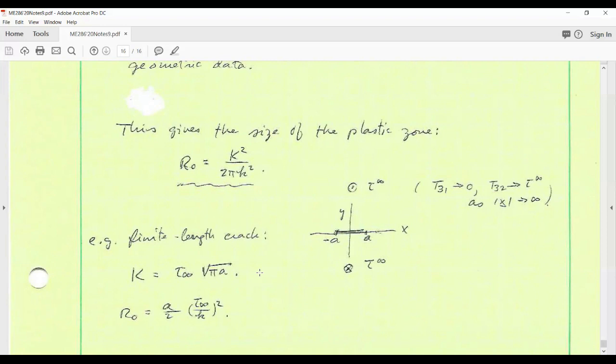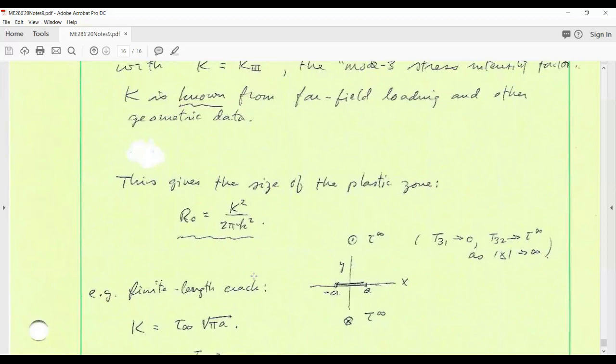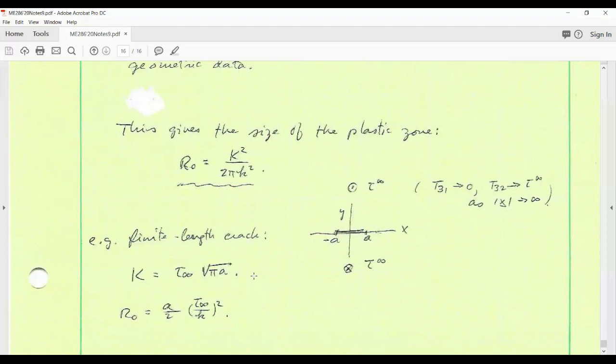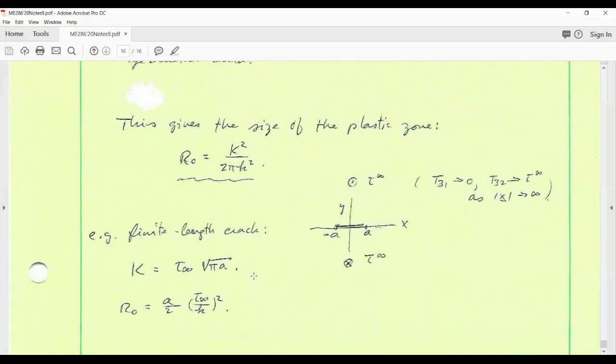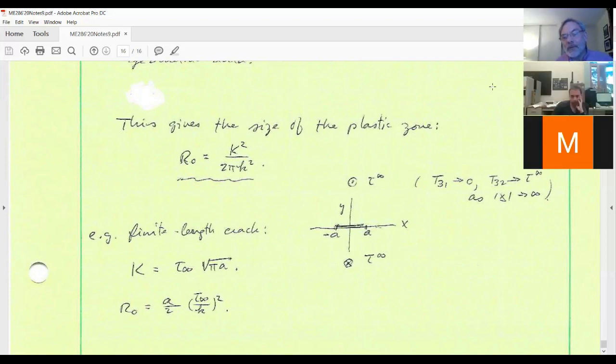All right, and so in homework, I'm going to ask you to verify that the solution we construct is admissible from the standpoint of dissipation. In other words, that scalar field lambda that appears in the flow rule is in fact non-negative in the plastic zone. By plastic zone, I mean a zone in which you can have both elastic and plastic strains existing. So the next homework will be the last homework, and I'll ask you to verify that. Okay, let's stop here today. As promised, this is an abbreviated lecture today, unless there are some questions, I should say.